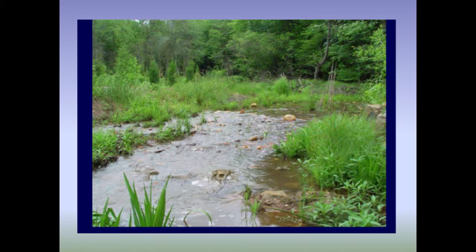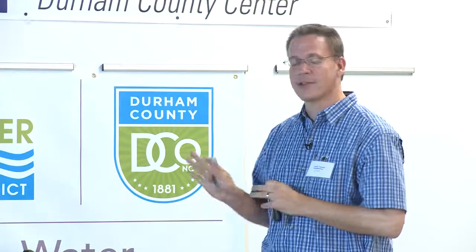So you can see there's a long flat area there. This is right after construction. A lot of that vegetation has been planted. You can't see it here, but they've actually included some low flow channel areas so that you can have a low base flow coming through there. And they were saying that they actually had to push that with their agencies to let them do that. But they did it from a standpoint of trying to improve water quality and get better filtration during storm flows.